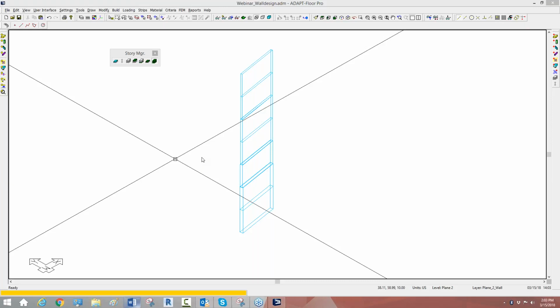You can. It's not explicit. The process for it basically requires you to build the walls such that you create an opening just by positioning and how the walls are modeled. We do have a video on our YouTube channel. If you go to that channel and type in wall openings, there is a video that talks about how you can model the openings in the walls. But it currently is done just by how the walls are modeled and linked together versus explicit dimensioning inside of a wall that has been modeled.